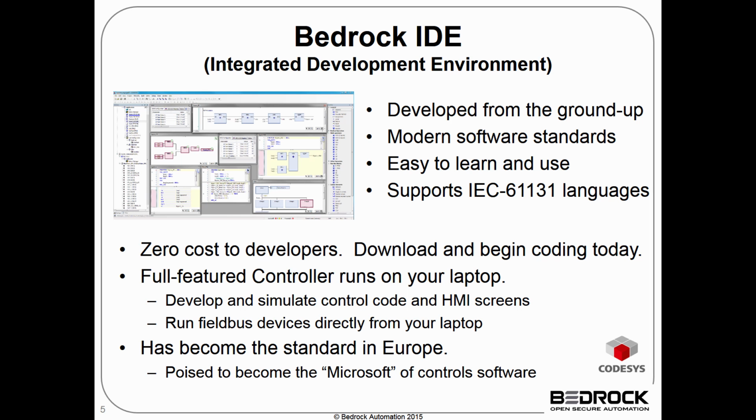The Bedrock IDE includes a full-featured controller that runs on your laptop. The simulator can run all of your control and simulation code, as well as make your tags available on its built-in OPC-UA server for you to develop and test your HMI screens. All this without ever touching any actual hardware. You can enter your plant knowing your software will work the first time, and the plant downtime will be kept to an absolute minimum when you deploy your new hardware and software.